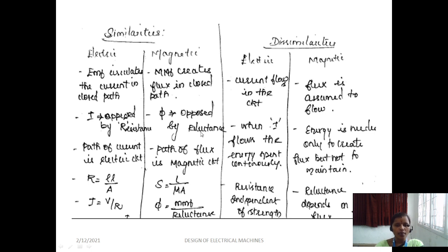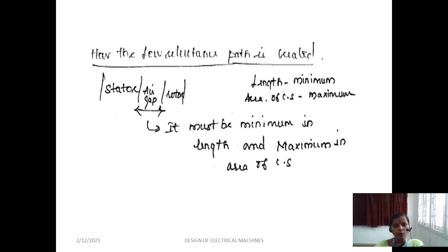then the proper electromagnetic induction given by Faraday will not happen. Therefore, when constructing an electrical machine, a main point to consider is that the reluctance, the opposition to flux offered by the designed magnetic circuit, should be lesser, so that more induction happens, which helps the principle of operation where you place your windings, in the case of dynamic and static categories of machines, right?